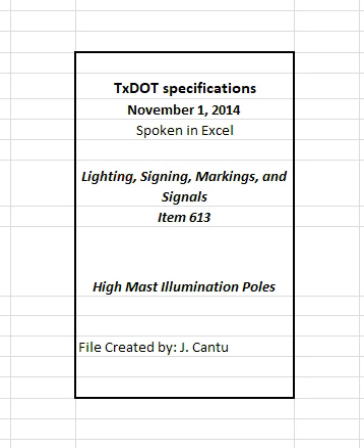3.4.2 Pole assembly. Assemble poles on blocking using a minimum of 2 hydraulic rams at the splices. Support the free end of the section being assembled with hoist equipment. Apply assembly force using hydraulic rams with sufficient capacity to properly draw the sections together with little or no remaining gaps. Mark poles with permanent ink to indicate designed lap length.